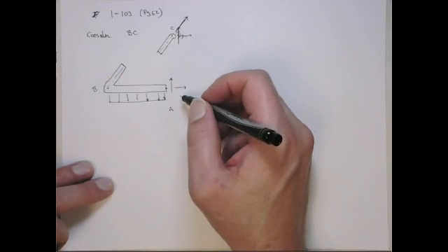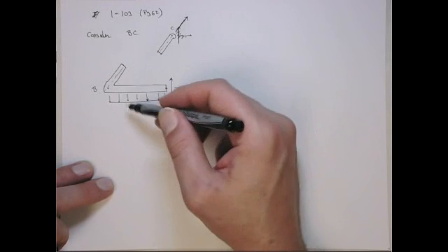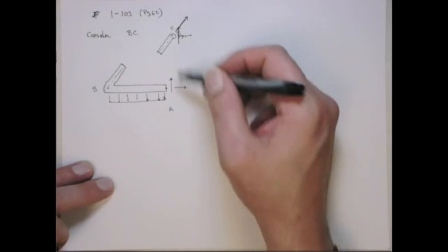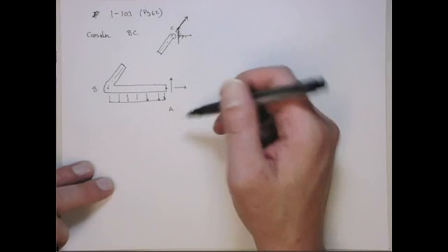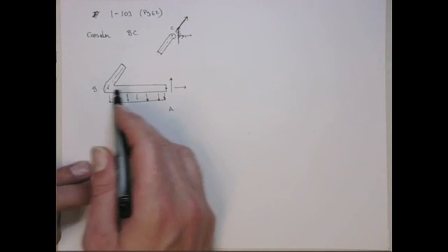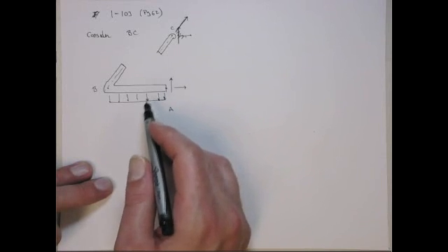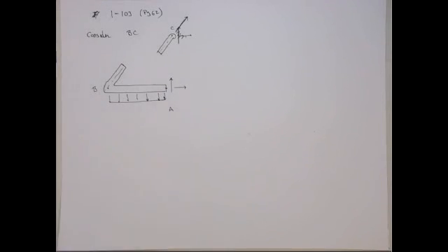At A, that's not the case. Although it's pinned to both A and B, we have this intermediary distributed load, which has to be compensated. And you can obviously see that from the free body diagram anyway. If we just act along AB, that'll give you this force, but you need a Y force to counteract this downward distributed load. Okay?